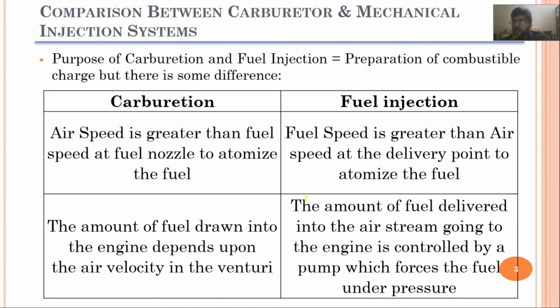When the fuel is injected at that time, when the piston is almost at top dead center, the speed of the fuel should be very much greater, so that it can penetrate across the air molecules and be sprayed throughout the combustion chamber, throughout the entire volume which is available at that time. So I hope it is clear now.